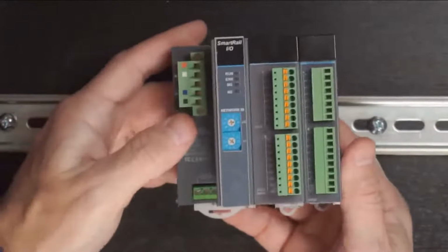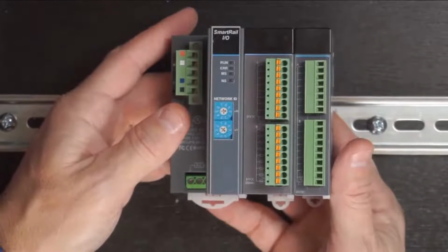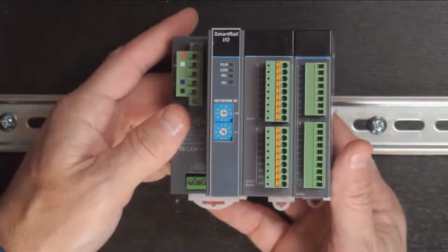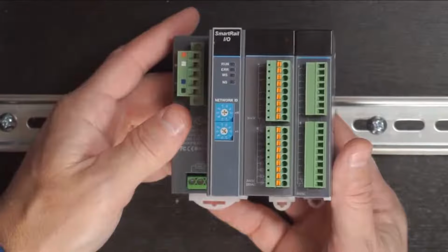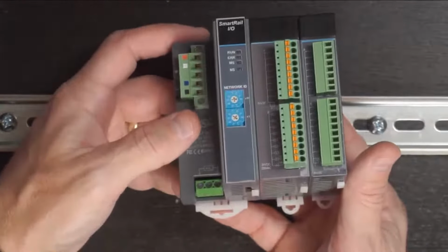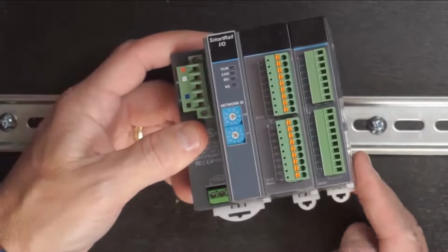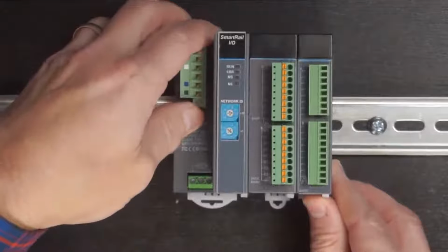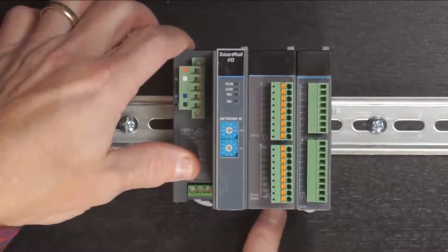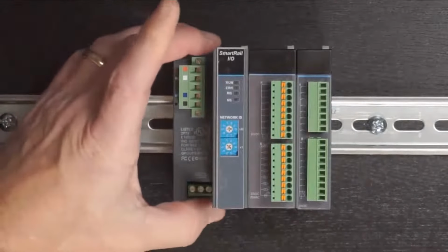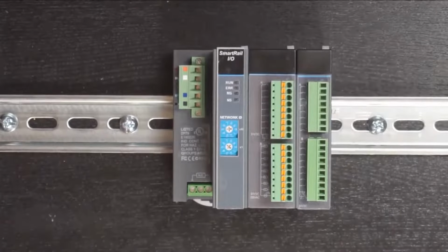Okay, there we go. Next, let's go ahead and put it on the DIN rail. Now you've noticed I did all my assembly while I was holding it in my hand on the bench. It's a lot easier to do that than to try and assemble everything while it's already on the DIN rail. So once everything is assembled, let's just make sure these DIN rail latches are in the fully extended position. And then let's go ahead and put the SmartRail on the DIN rail, push down, and then close each of these latches. Now everything is in place exactly where we want it. We're done with the mechanical assembly. Now we're ready to talk about electrical assembly.